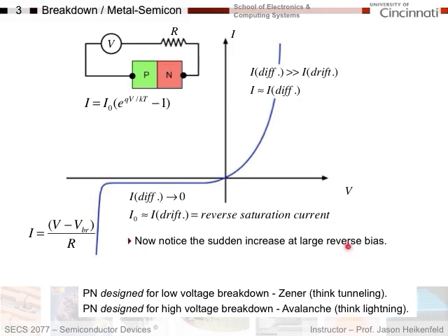Basically, you've got your contact potential minus the breakdown voltage. So your breakdown voltage, how much voltage are you applying above the breakdown voltage? And so if the breakdown voltage was 4 volts and you're applying 6 volts, you'd have 6 volts divided by the resistance of your circuit. And I put a resistor here, but you don't have to have a resistor in the circuit. The semiconductor materials themselves have resistance. And so this resistor could just be representing the inherent resistance of the semiconductor materials themselves. The point is, on this plot, once you get to breakdown, you get a very large increase in current.